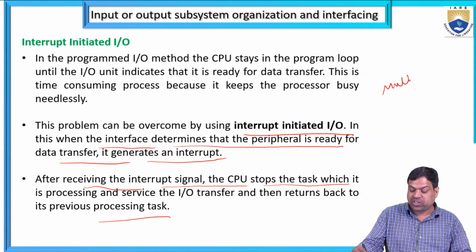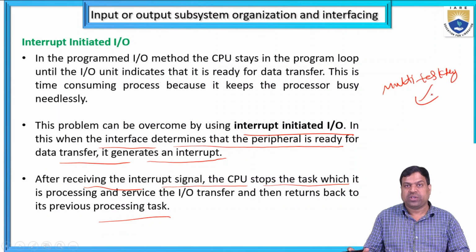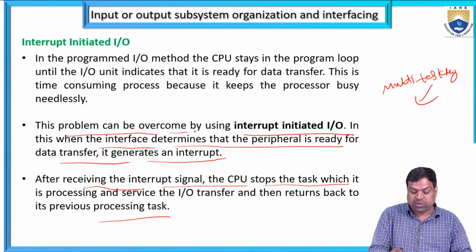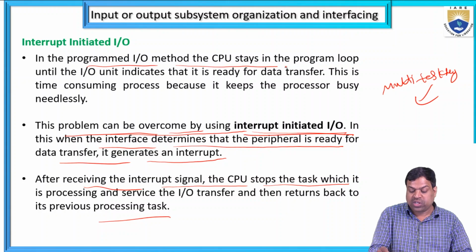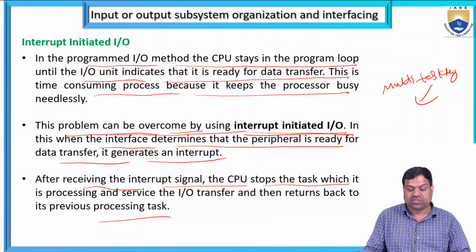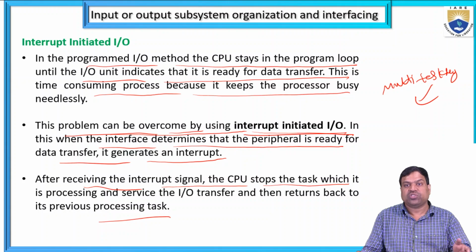When I am going for multitasking, or multi-programming, only then do I have to use interrupt-initiated I/O. So the problem can be overcome using interrupt-initiated I/O. In programmed I/O, the CPU stays in a program loop, which makes the data transfer a time-consuming process because the CPU is busy. In interrupt-initiated I/O, the CPU receives the interrupt signal from the interface.